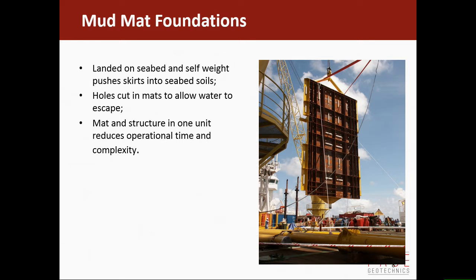There are some people do design a grillage foundation which is designed to penetrate to a depth in the seabed. That can have some advantages, particularly when you're lowering it through the water column, because one of the problems with these things is if it's going down horizontally, it's got a huge hydrodynamic drag. Or, you know, if the vessel's moving at all, it's trying to go up and down, so if you don't have a heave compensated crane, it's a real problem.